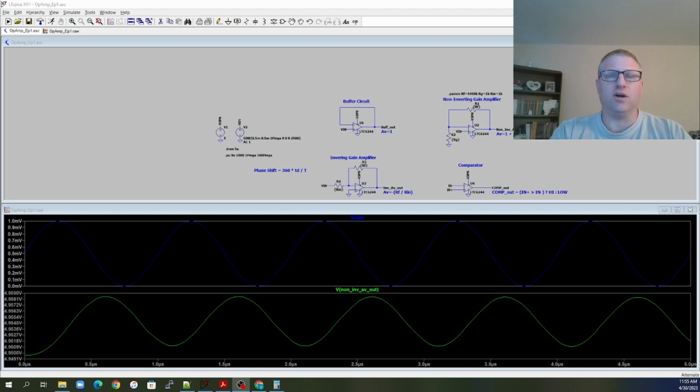And then we also saw what happened when we tried to exceed the slew rate capability. We saw phase shifts. We saw outputs that were not fully gained, right? Because the slew rate wasn't fast enough. So whatever our application is, we've got to stay under that slew rate. We've got to stay under the VCM for the inputs. We've got to maintain our output parameter, right? This was a rail-to-rail one, so we could go all the way to 5 volts.